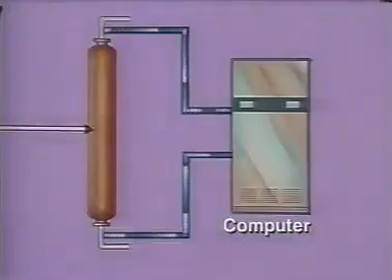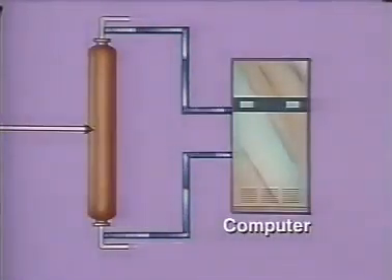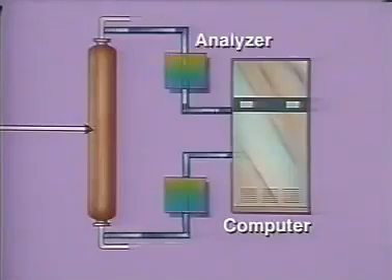More effective control of a series of towers is realized by using chromatograph analyzers in conjunction with a computer. During normal operations, a computer-based system makes closer cut point divisions than conventional instrumentation. This saves energy and allows us to recover more of the valuable components.